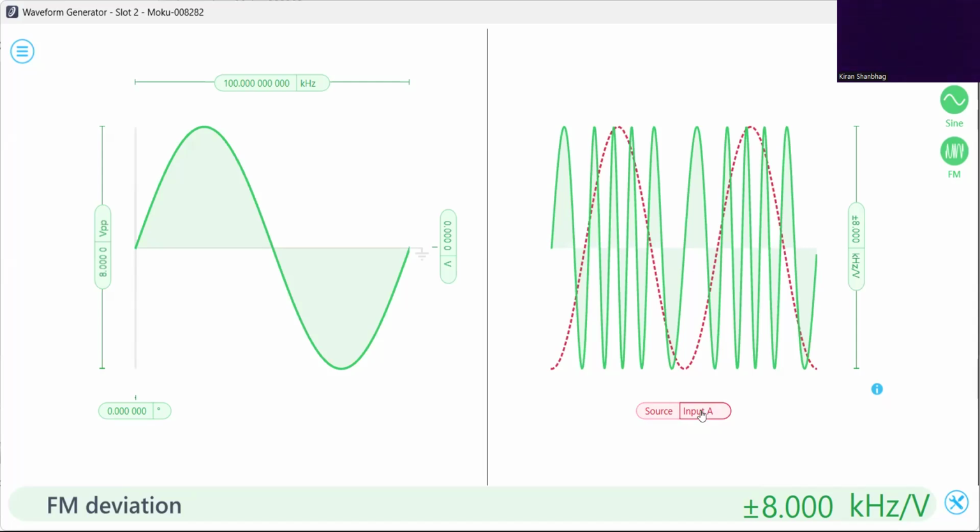As I told you, my oscilloscope has a square wave. I'm taking one square wave input, the message, from the oscilloscope. That will be my modulating input. And the other one is the carrier, which is here. So that is a sine wave. Okay. Then I get to see my output A from here.